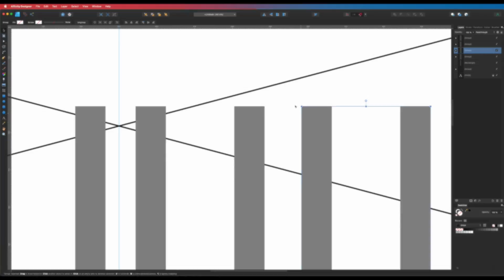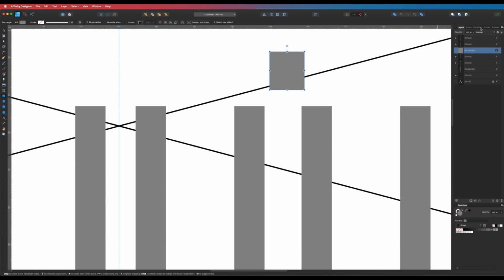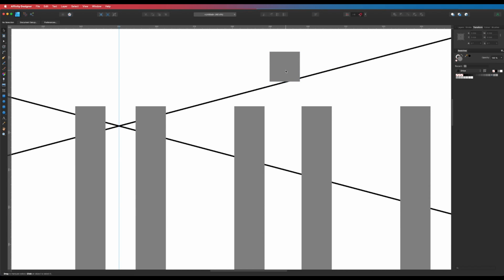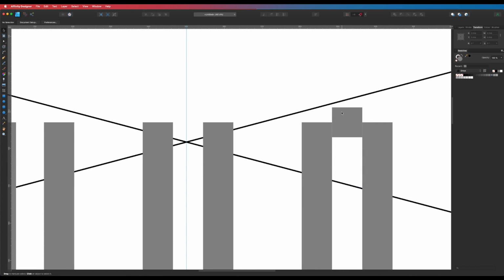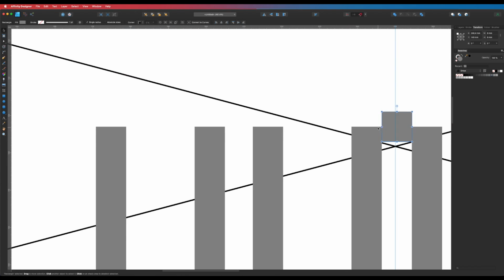So the only other way around that is to just draw a block, go the old-fashioned way. Hit M, draw a square, make this square basically 8 mils. So I'm going to go 8 by 8. Okay, so that's just an 8 mil square over there. I'm going to snap it to that one, snap it to that one. Now I know I'm 8. Then that one we knew was 8.